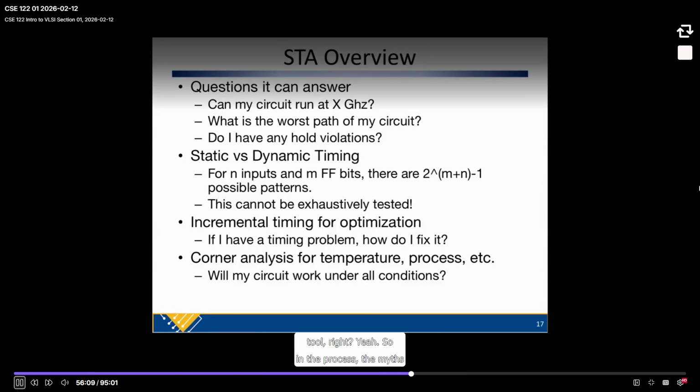Yeah. So in the process of a tool doing that, is there any level of randomness, or rerunning the tool multiple times to get different results? That's a very good question. The answer is yes. Usually that's a bug in the timing analysis tool. Sometimes it's very hard to replicate. You want it to give the same answer all the time, but something can sometimes change and give different results. Usually it ends up being rounding errors that then affect a decision that then changes your result.